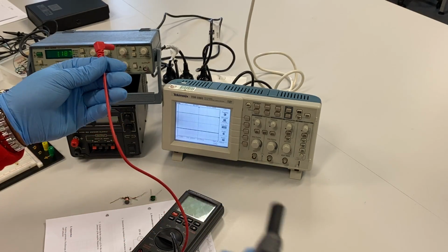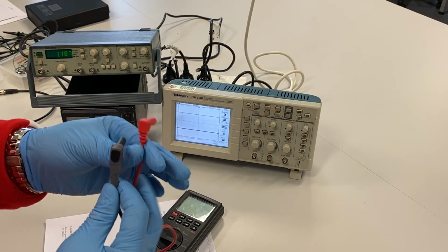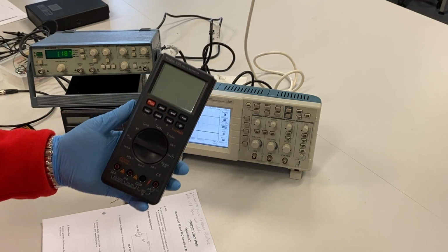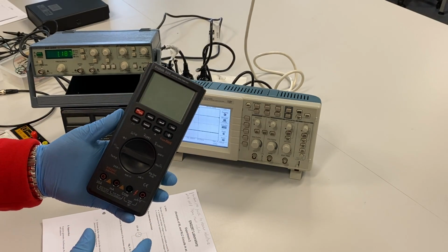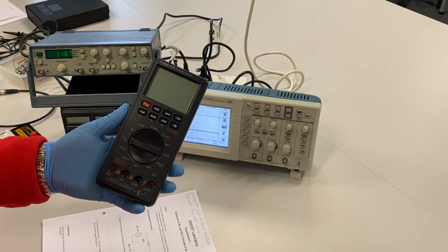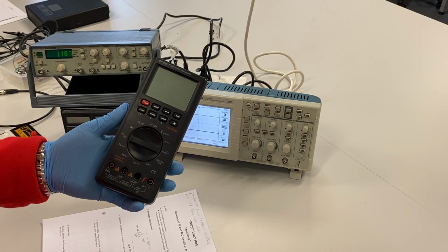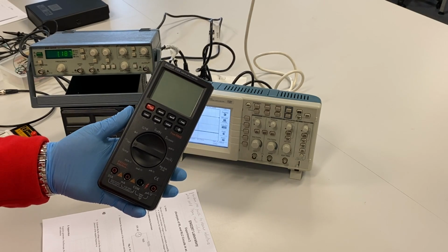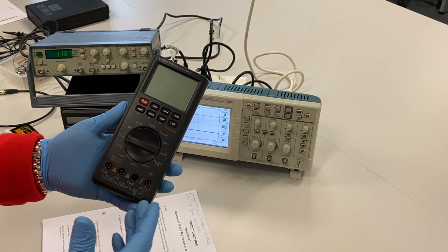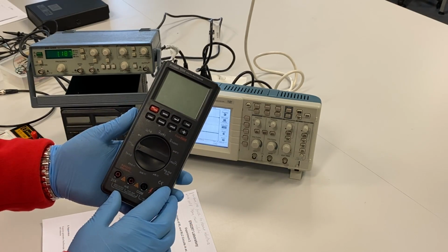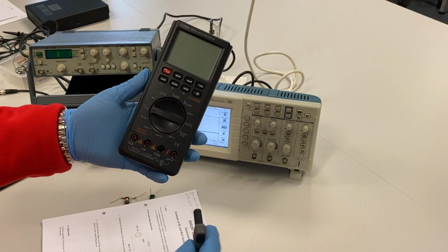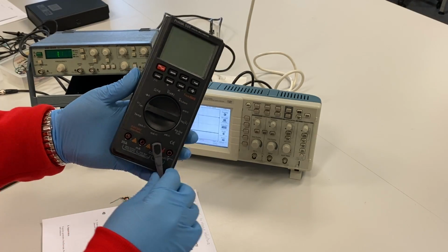Like black, we usually put it on the ground, and red, we put it where we want to measure current or voltage. So it's a digital multimeter. It measures RMS values of current and voltage, but not only that, it can measure inductance, capacitance, and whether a diode is working or not. You see, when we start using diodes. It can measure frequency and many operations. But what we do is we always keep the ground on the COM.